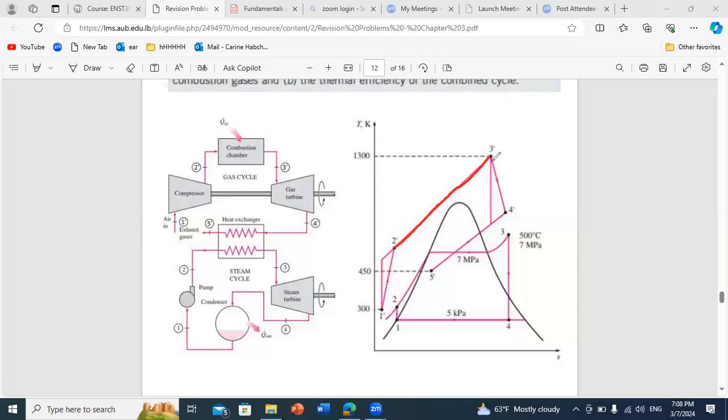I just have a small increase in the entropy S. And then I move downward along a constant pressure line, and it's limited by the exhaust temperature, which is 450. While for the compressor, since it's not an isentropic process, it's not vertical, it's a little bit inclined. So this is how I can draw my figure. Okay, any questions on this?